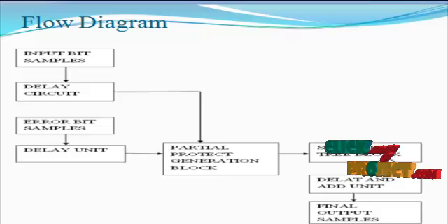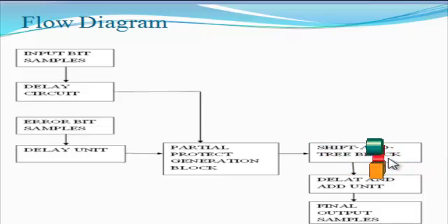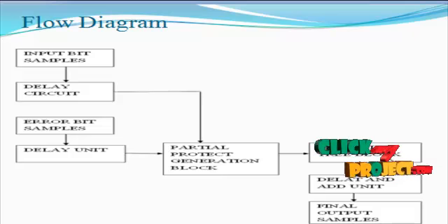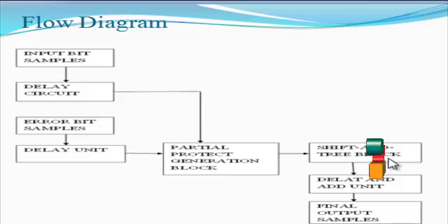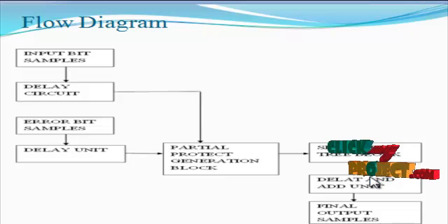This process is mainly used to reduce the carry propagation time and to reduce the hardware complexity of the shift add architecture. Then the shift add architecture result is applied to the delay and adder element. The delay and adder element is mainly used to store the results in registers, then to produce the final output results. The delay element is mainly the D flip-flop register element.